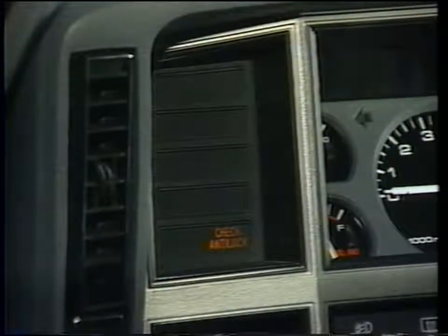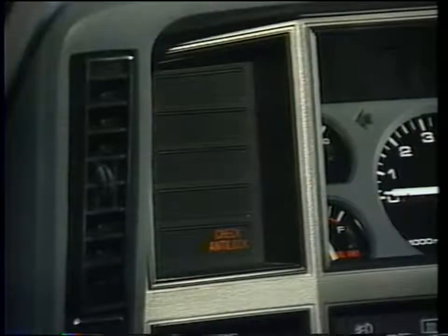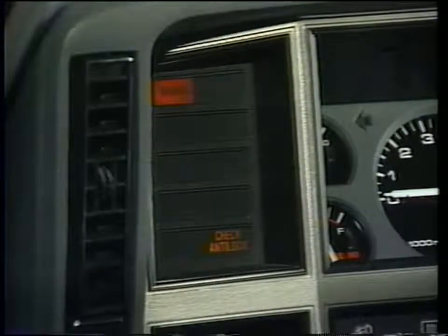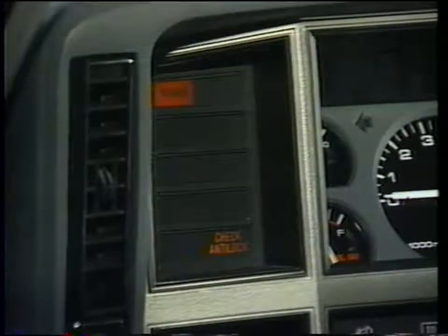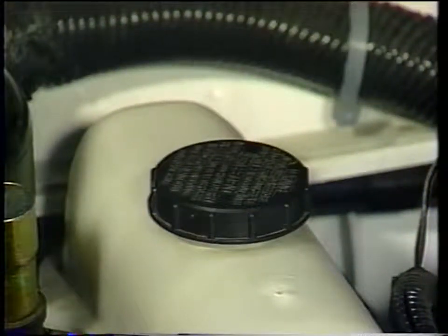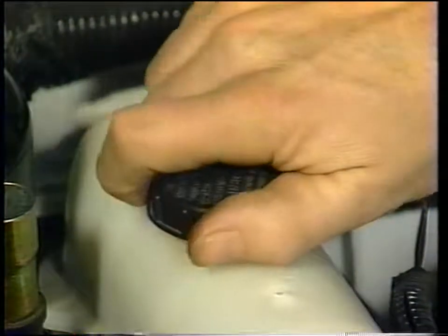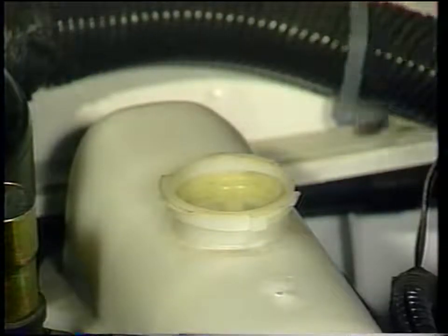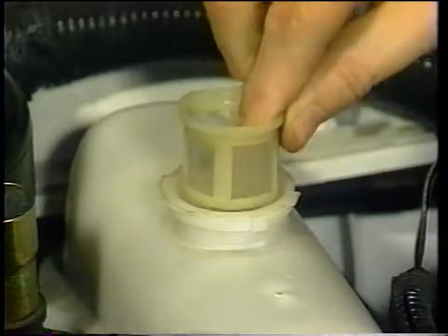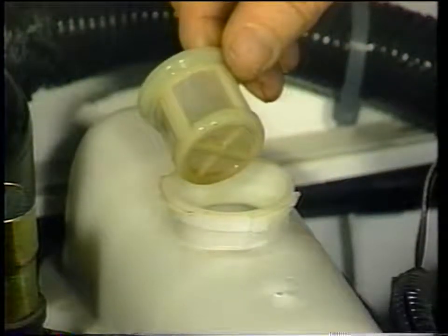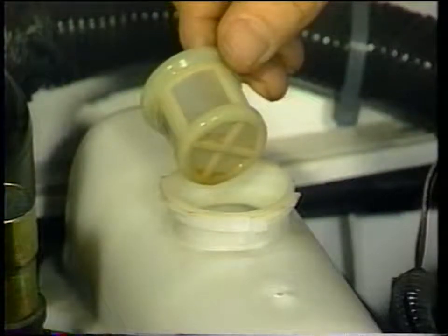If accumulator pressure does not increase enough to close the switch within 20 seconds, the red brake warning light will also come on. The 3 switches we've just described, plus a small filter located under the reservoir filler cap, can all be serviced separately. Be sure to check and clean the filter when doing brake work on this system.